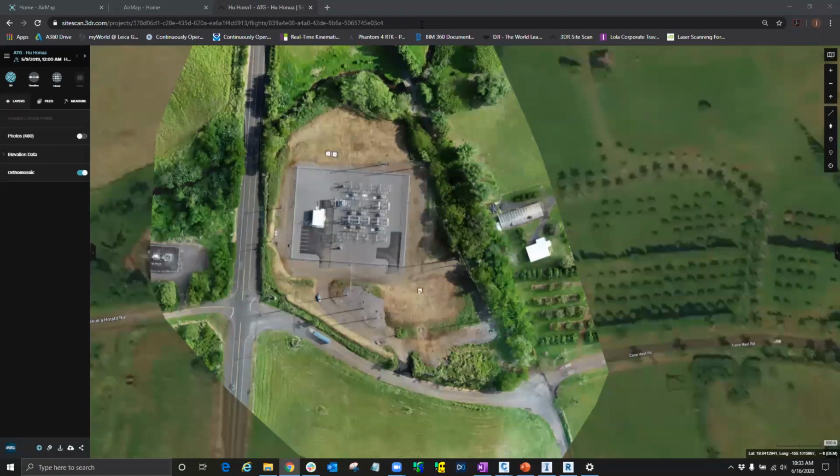And part of that is what we ran through with the ground control points. We can have a local surveyor go out and survey some control and checkpoints for us, give us that CSV file, and then we can upload that. When it does the processing of all the photos, it's going to make little tweaks and adjustments to make that more accurate based on our survey control.